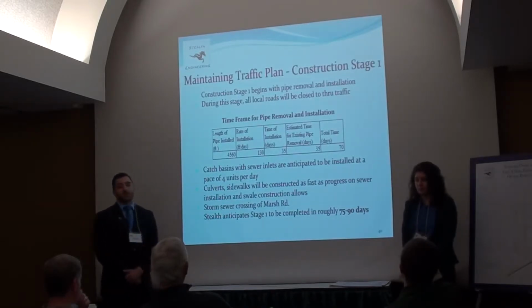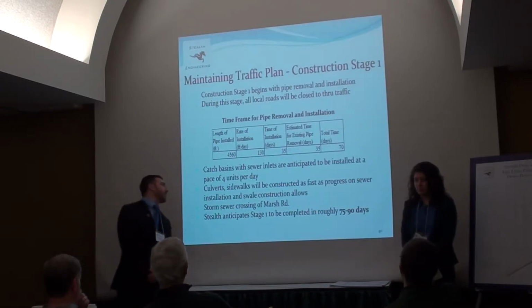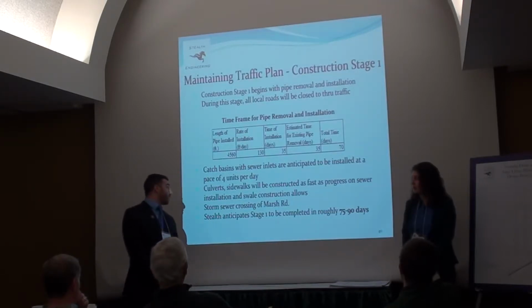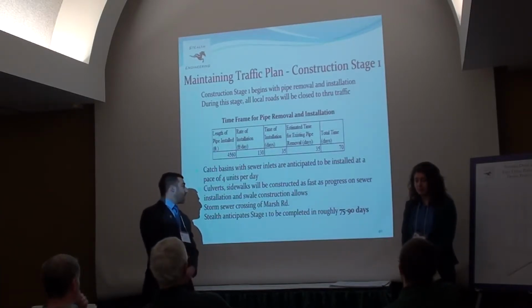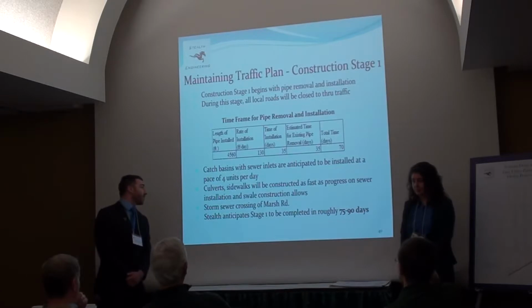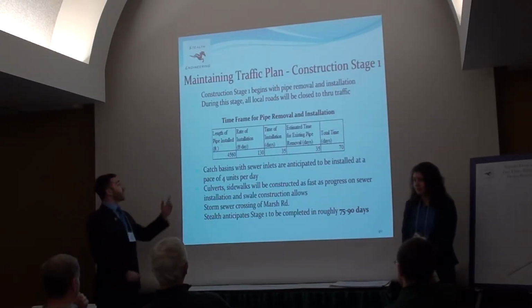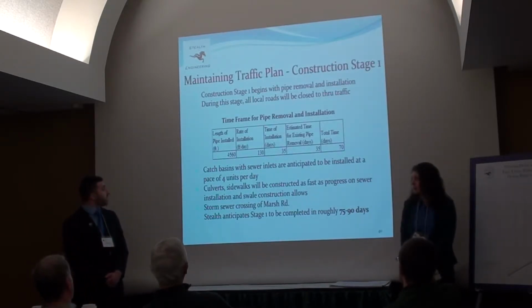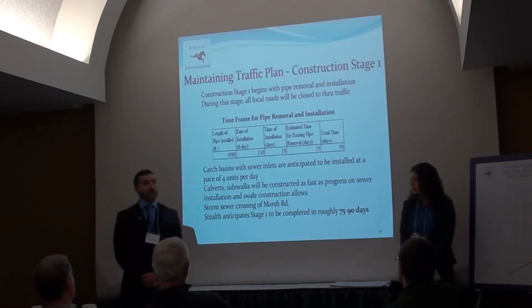Using, again, the Michigan roadway design manual, it was determined that catch basins with sewer inlets could be installed at a pace of about 4 units per day. And furthermore, any culverts needed at driveway approaches and sidewalks essentially can be constructed as fast as progress on sewer installation and removal allows. One thing to consider again for stage 1 is the storm sewer crossing underneath Marsh Road. With all this considered, we anticipate stage 1 to be completed in roughly 75 to 90 days.